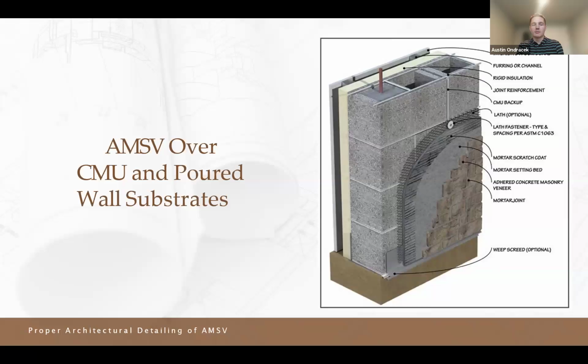Similar to that, when you look at maybe a concrete masonry unit or a CMU, a lot of masons or installers will apply stone directly onto a CMU. You can do that. It's not like it's not allowed. There are best practices that would say put a metal lath on, have that substrate cleaned, and have that barrier that you know is not contaminated, or maybe there's mold or whatever type of elements that have been on that masonry unit for many, many years.